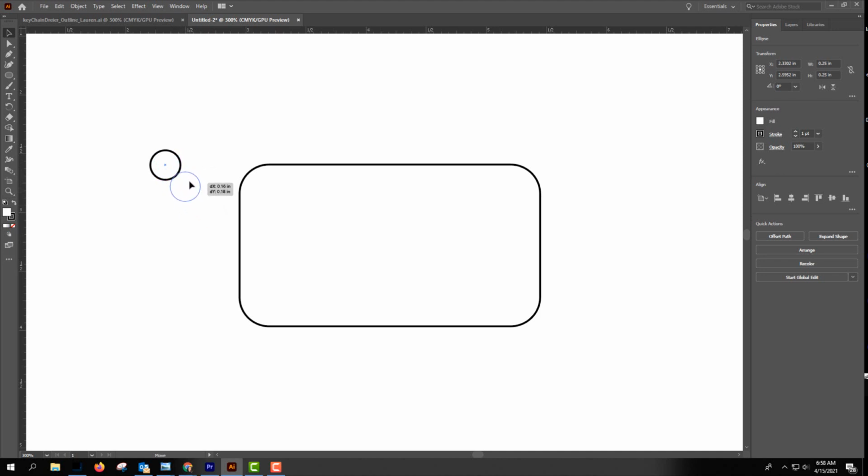And you can see as I'm moving it that we've got some pink lines showing up. Those are the smart guides, like do we want something tangent, but in this case what I'm going to do is mouse over until I get this pink line. That's really the center of the whole fob here. Now you can choose where to put that.